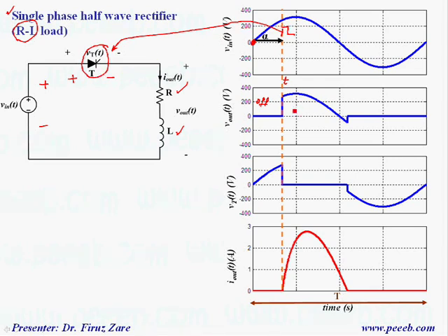So what happens when we turn on the thyristor? Input voltage appears across the resistive and inductive load, so then we can increase the current. So the current through the thyristor, that means load current, is increased. And the point is that at this zero crossing point, if you look at the load current, the output current is not 0.